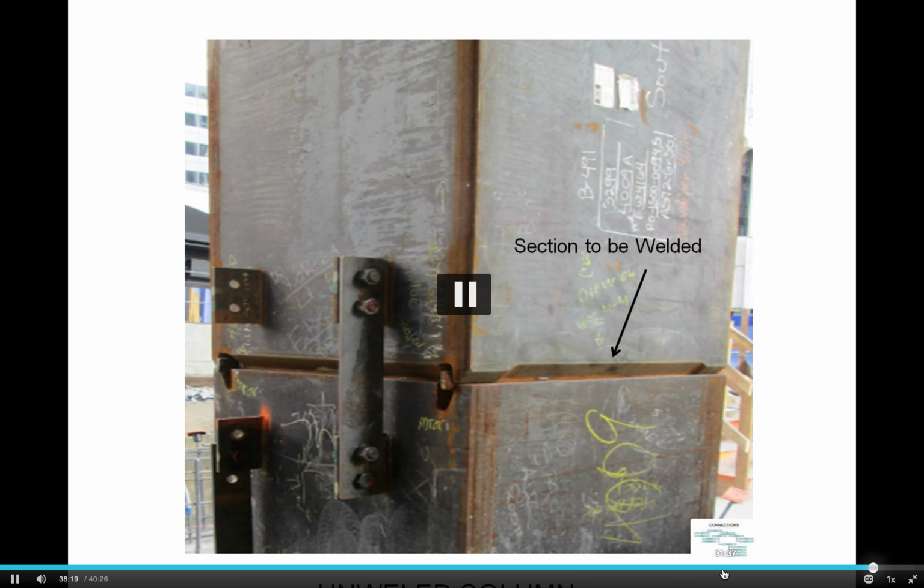The very skilled welders out there who do this work understand what needs to be done and know how to do it. And welding on a building is very difficult because, again, you saw that column, that beam connection. Imagine having to do that 20 stories up or 30 stories up, lying on your back, probably tied to a beam. It's just difficult to do. And that's why you try to bolt as much as you can in the field and weld as much as you can in the shop if you're going to use welding.